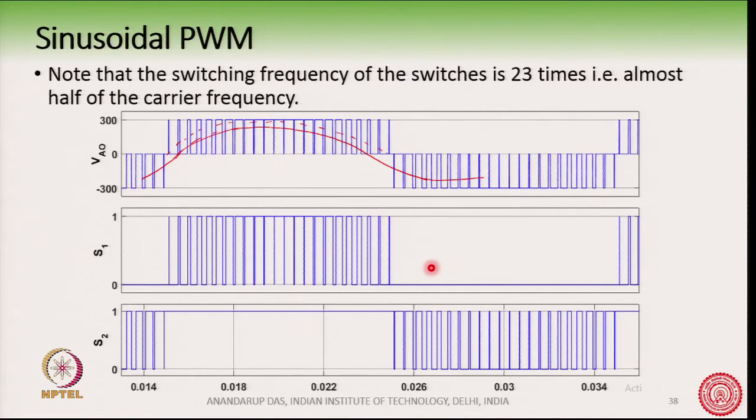In general, this is one of the challenges of NPC. For close to unity power factor and high modulation index, the outer switches of the NPC have much more loss than the inner switches. So, this is an uneven distribution of losses in the converter.